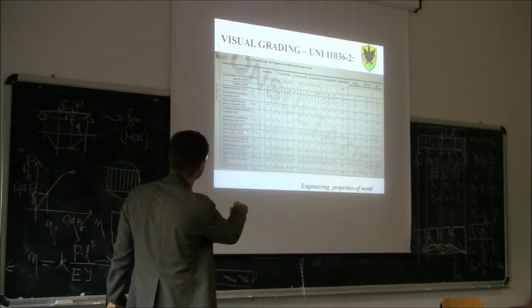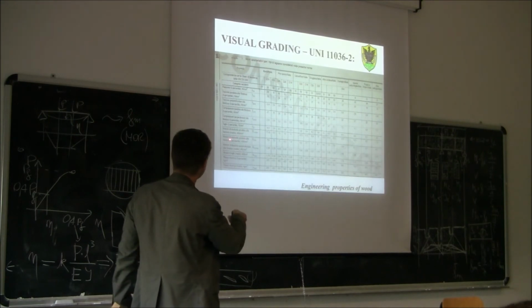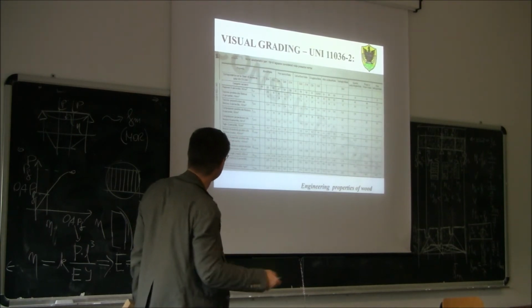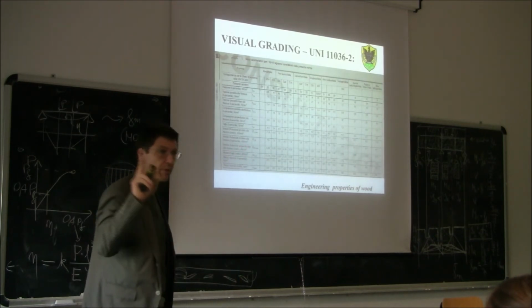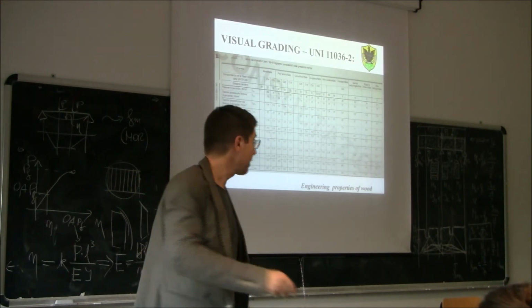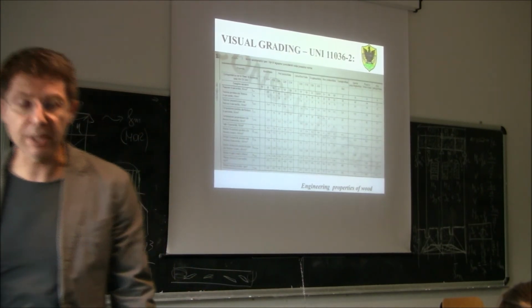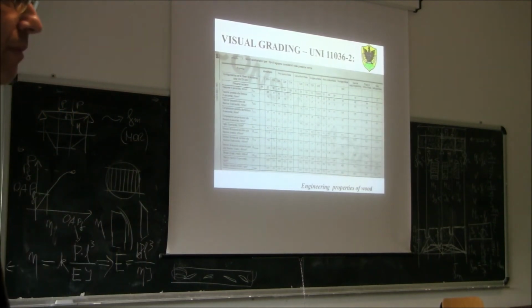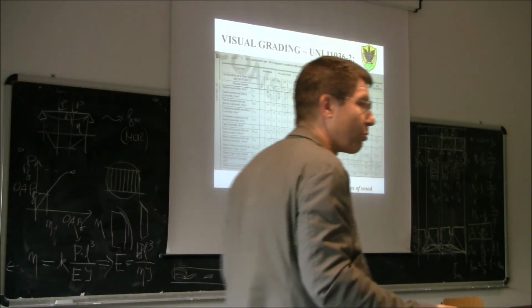So we have the mean modulus of elasticity parallel to the grain, the characteristic modulus of elasticity parallel to the grain, then the modulus of elasticity perpendicular to the grain, and the shear modulus: 4 properties. And then density, characteristic and mean density. Why so many properties? Why do we need so many strengths, for example, when for concrete we need only one value, for steel only one? What is the most important difference between the two materials?